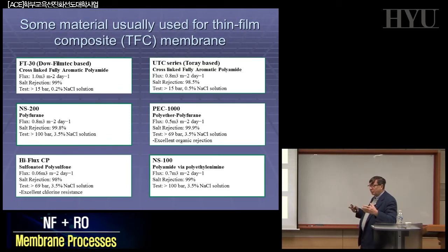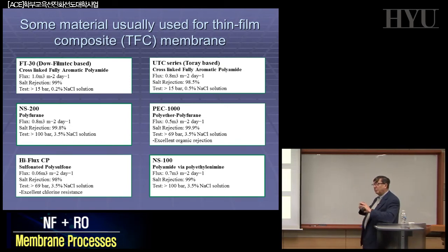You can produce asymmetric membranes by phase inversion. That means having one polymeric solution, and if you know how to do it, starting from what we call a polymeric solution with solvent and non-solvent present, you can evaporate and you can go from liquid phase to the solid phase. And this is what we call phase inversion.